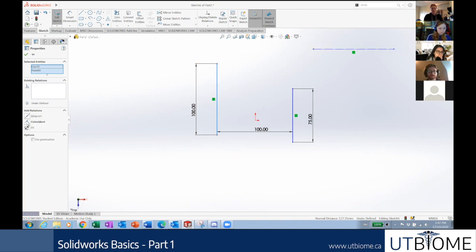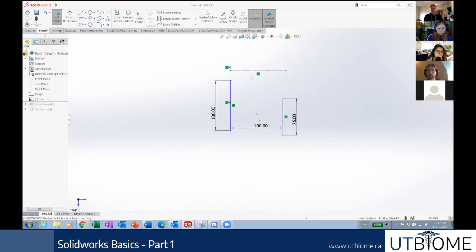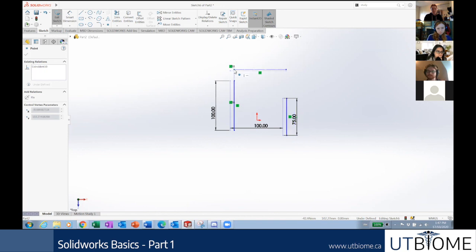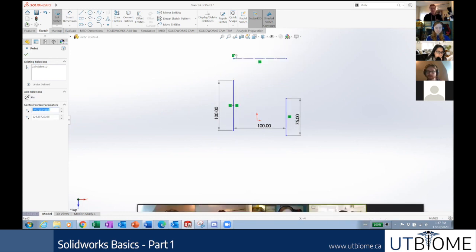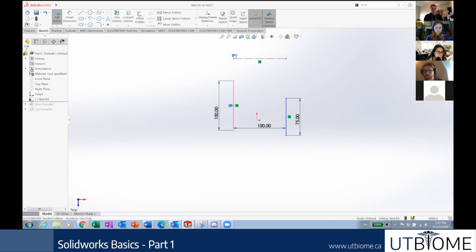I'm just going to set it to show you, and I can delete this after. It doesn't have to necessarily be on the line, but I can't move it. We didn't define the rest of it, but basically it is always going to be vertical of this line. I can't put it out of sync. It is always going to be in relation to this line, but it's not at a specific point on this line. And I want it at the center of this line. So I'm just going to click on this relationship.